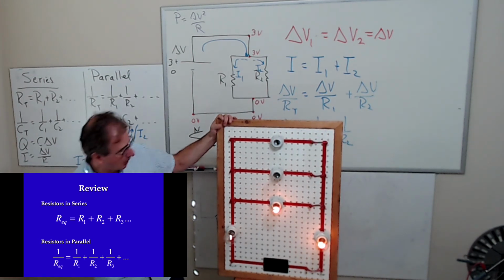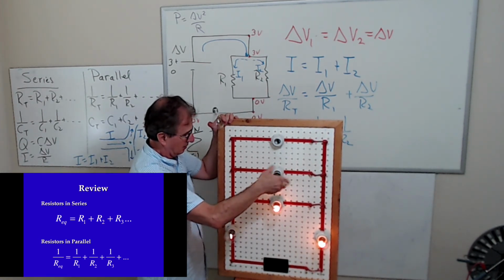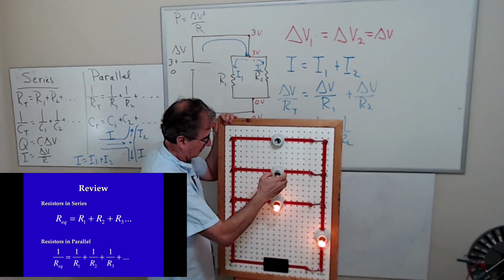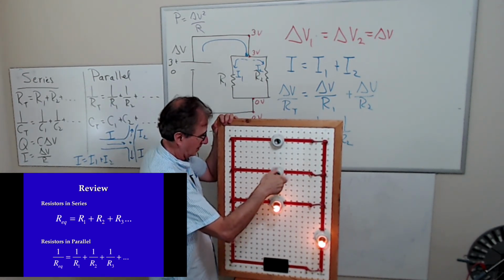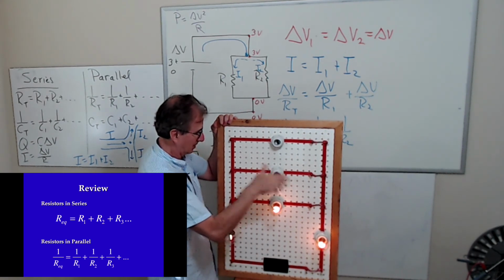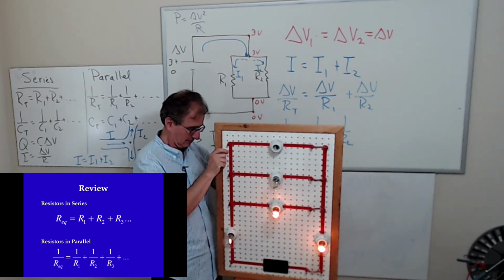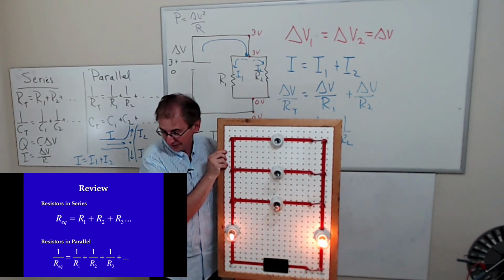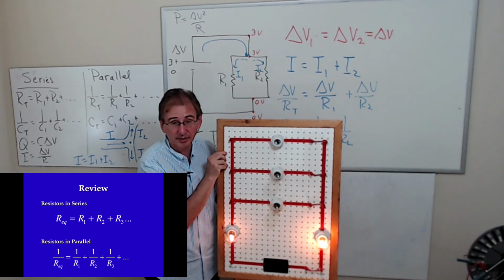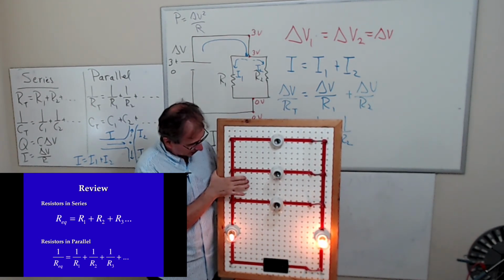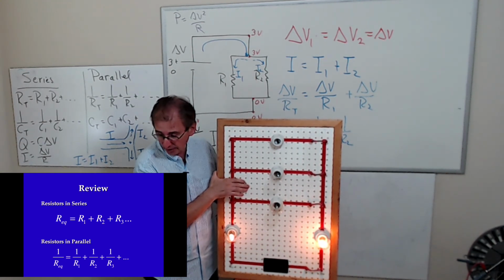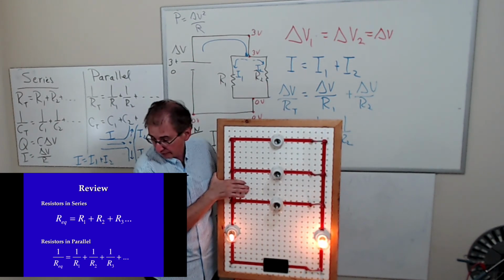Yeah, let me do it with the 60 watt bulb. Let me put the 60 watt bulb in. In fact, it goes completely off, right? That's the 60 watt bulb and a 25 watt bulb in parallel. So now because these two resistors are in parallel, the combination of the two resistors is going to be smaller than either one. That's why this one goes off.